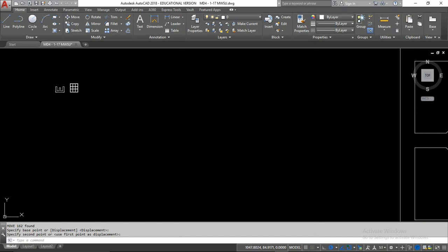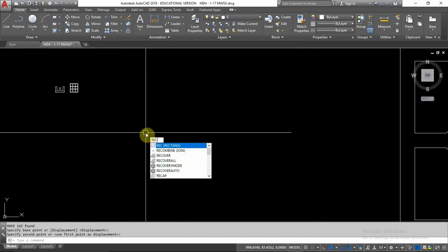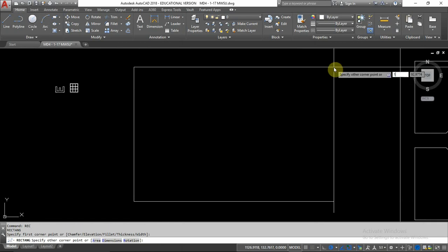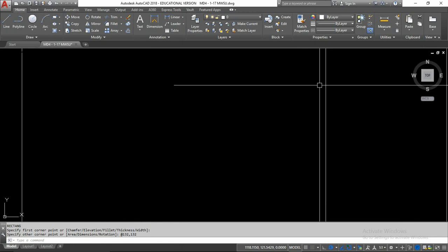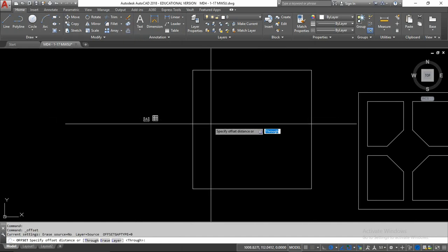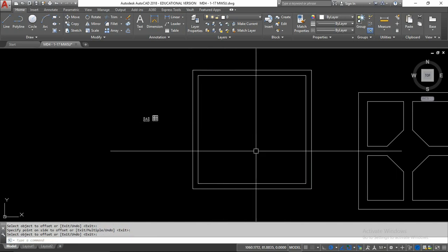So move that over. I'm going to go ahead and do rectangle, REC. And I know this is 132 square, 132 comma 132. And I know that there is another square in here set in a unit of 6 millimeters. I will use the offset, O6, click, click. And then I have these little squares.